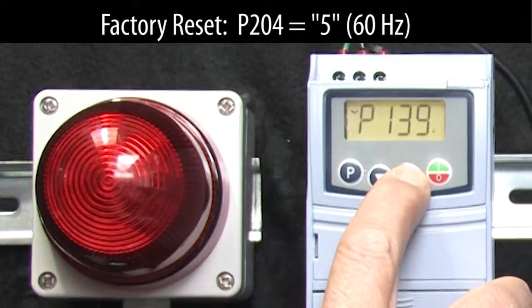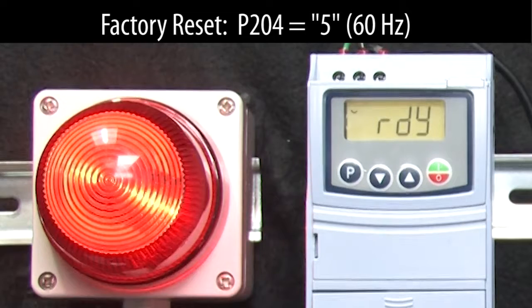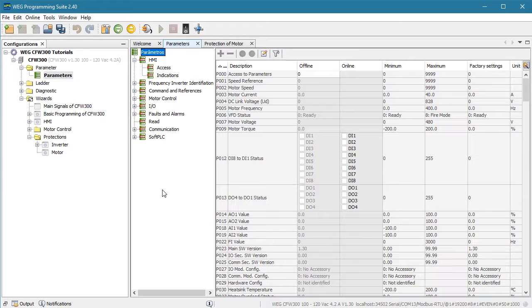Let's do a factory reset so we're starting from a known configuration. And sure enough, the indicator's lit, telling us there's currently no fault. Exactly what we expect. This is the free WEG programming software, or WPS. It isn't connected to my drive right now. I'm just going to use it as a quick parameter lookup tool.